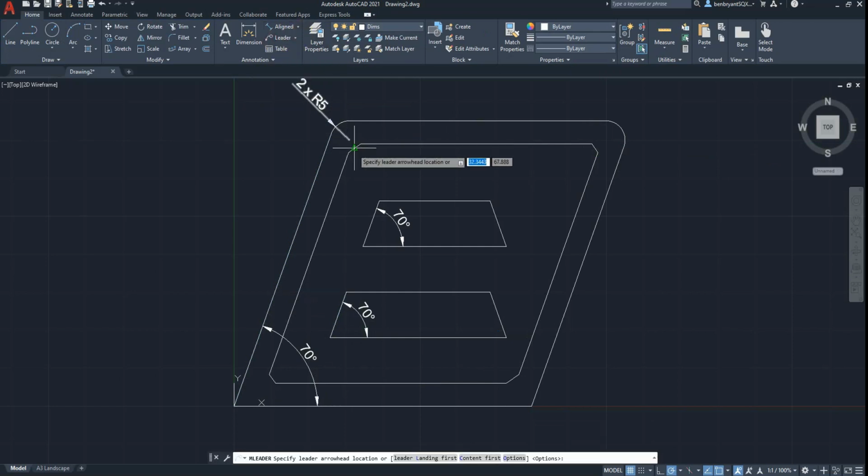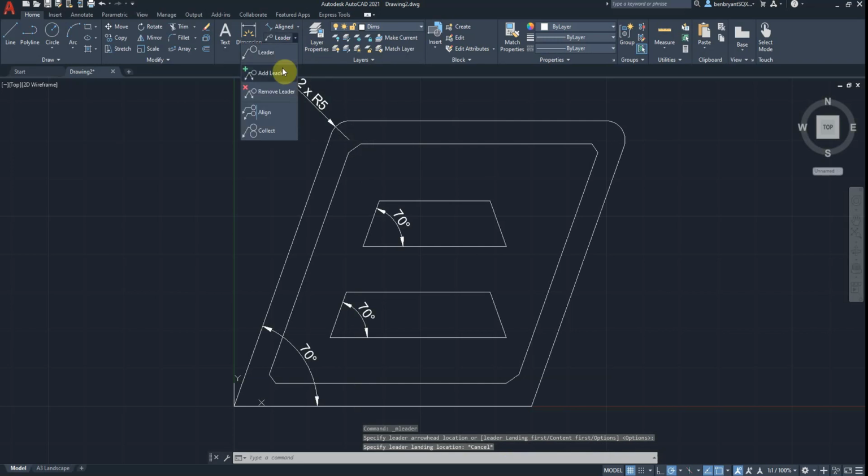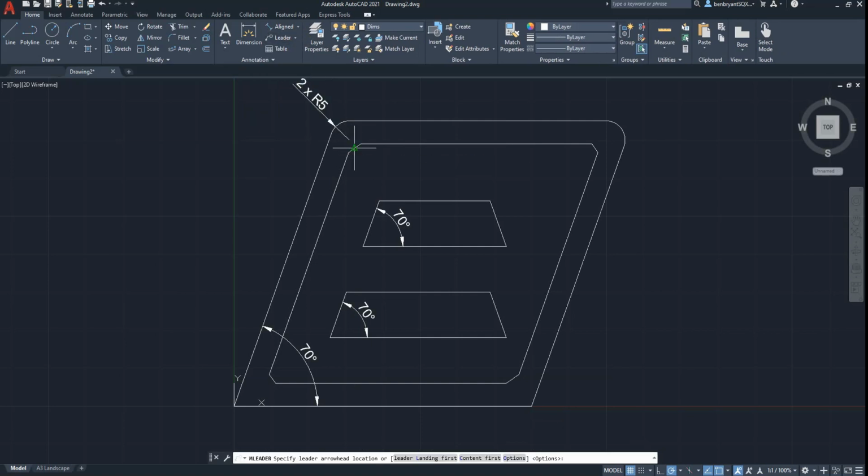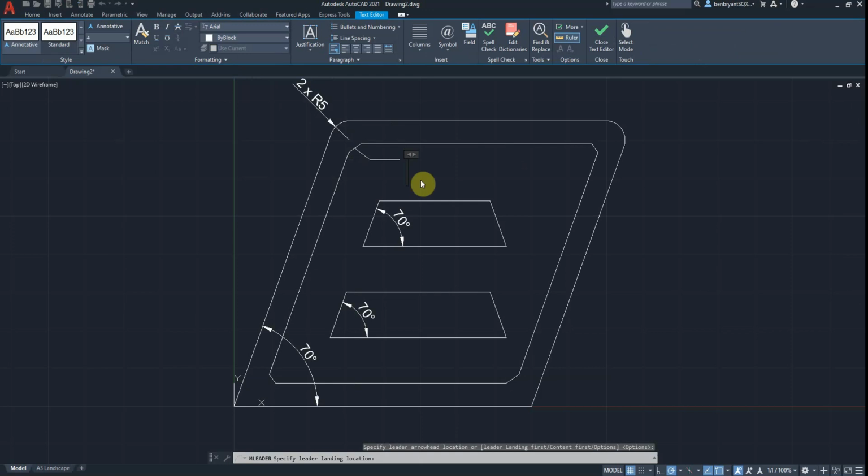So what we do is we use a leader line in here, so you can add a leader. Oh, sorry, leader. And this is what I would put in here. I change the size down to like 2.5, match it in with your dimensions. Maybe 4 times 2.5. Did I do times again? Yeah, times 45. Now remember the degrees is in the symbol here, like so.